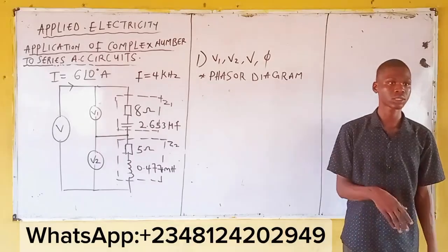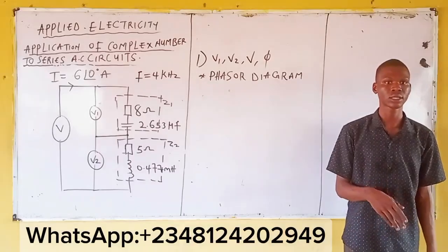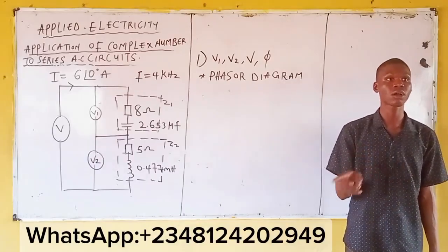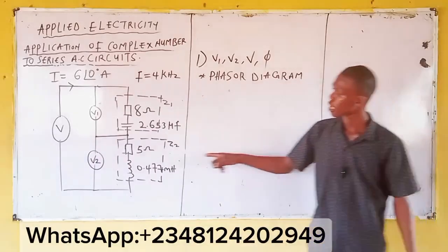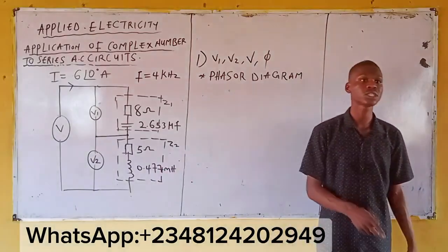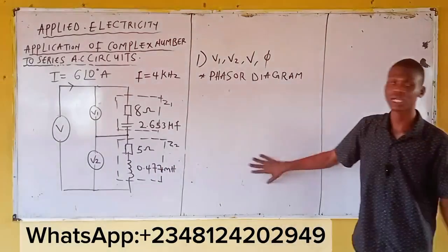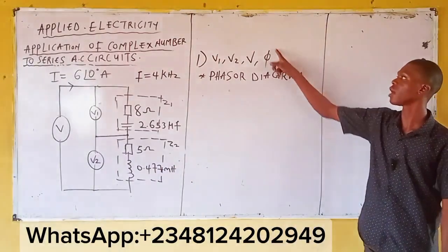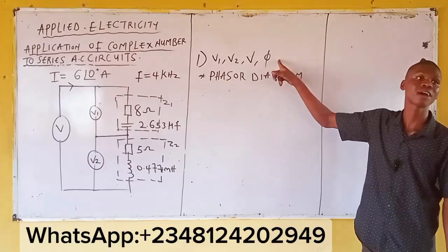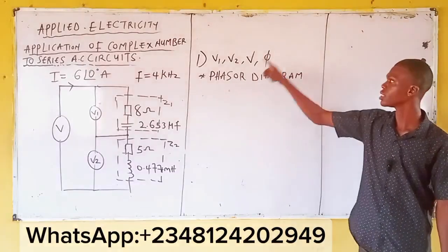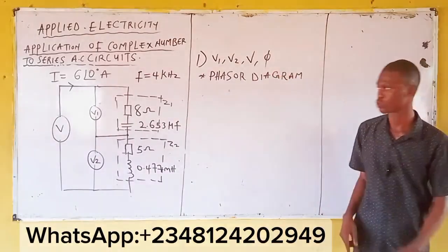You know, we said for inductor, what's lagging and what's leading? For inductor, voltage leads, meaning current lags. For capacitor, voltage lags, current leads. Now, this is where the idea comes in. By the time you get your value of this phase angle, you now write, is it lagging or is it leading? Now, solution.